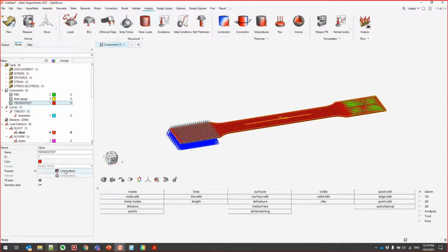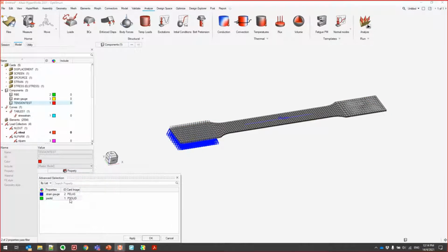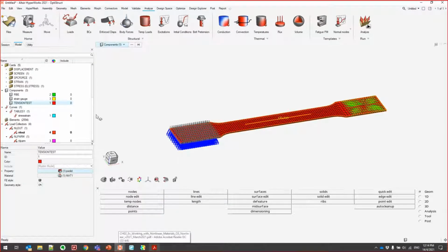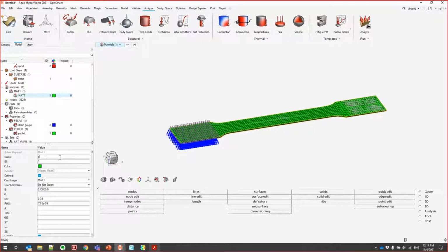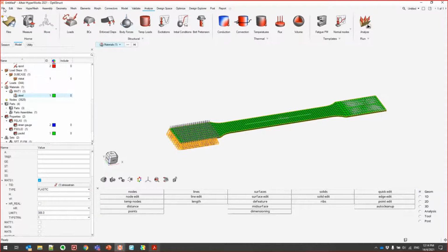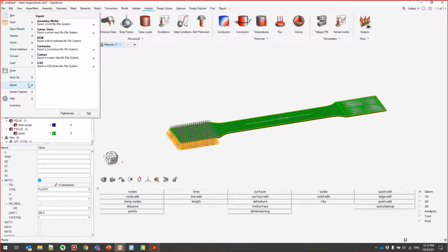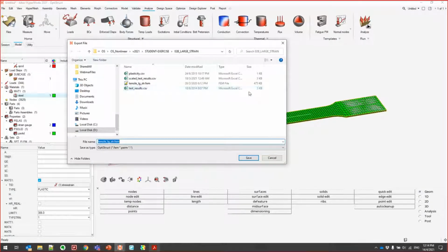Double check on my material. Yeah, so I need to define it as PSOLID. Material MAT1. Okay, even though it's called MAT1, let me just rename this. It's a bit confusing. So I just call steel. This steel is actually MAT1, but it also has the MATS1 defined as well. Right, so let's output this one. I should save it under here.